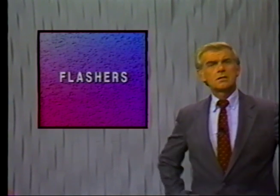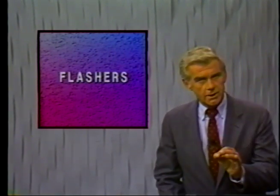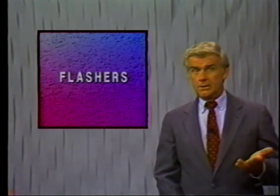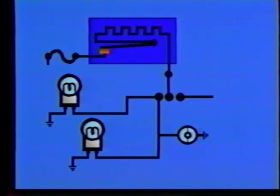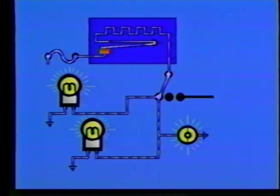To choose the correct response to this comparative statement, we must understand how the flasher works in the circuit. Flashers are, in essence, bimetallic self-resetting circuit breakers designed to operate at specific amperage. When the directional switch is closed, current flows through the flasher to the front and rear directionals. As the current flows, the flasher heats up and opens the circuit. Then current stops and the bulbs go out. The breaker cools, remakes contact, and the cycle repeats itself.